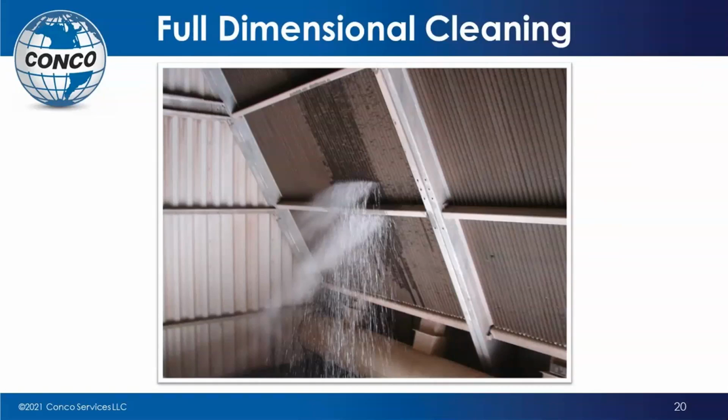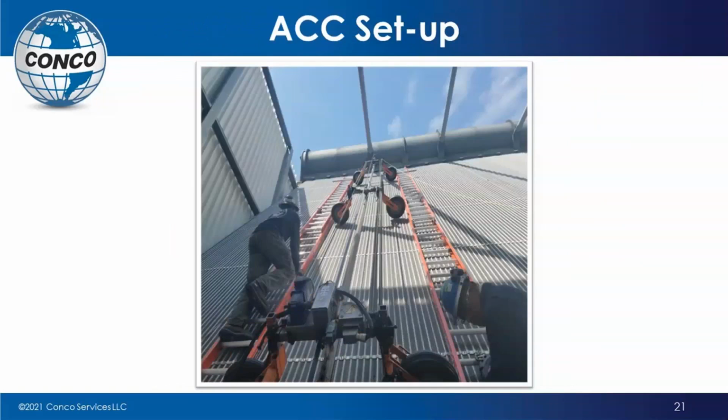So this is a way to get in there, take a look at the cleaning itself, how it is cleaning, and what kind of results you can expect. Of course, once this is done, you can always get down and take a look, and you should be able to see up through those fins up into the sky, and that tells you that you got a good cleaning.